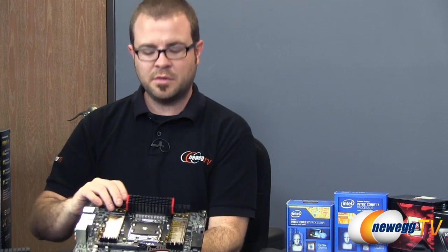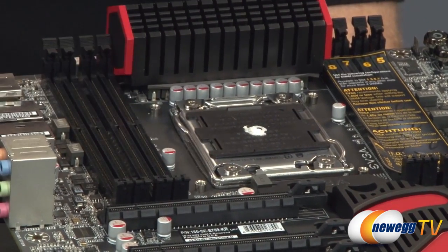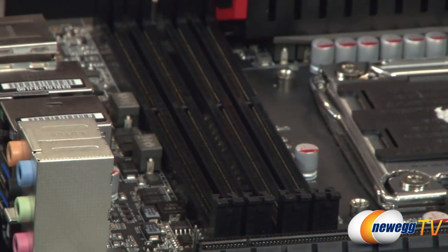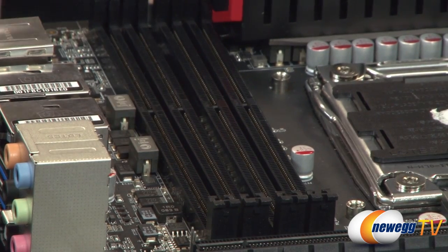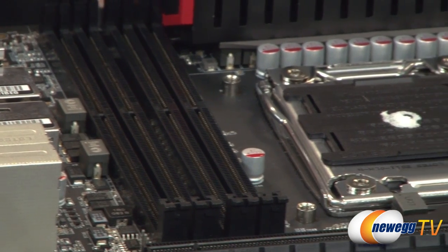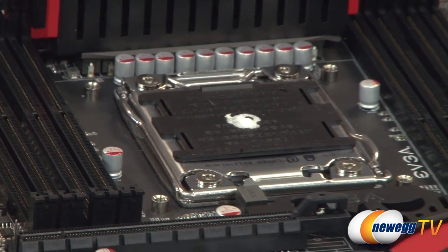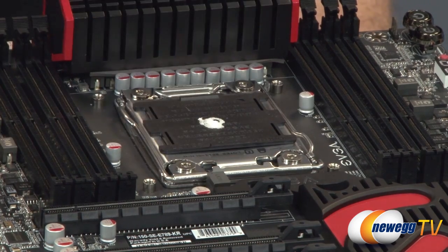For Intel's enthusiast platform right now, X79, right here, for example, it actually uses what's called quad channel memory. So let me pull a sticker off. You notice you actually have a total of 8 memory slots on this motherboard, and it's set up in sets of 4. Your motherboard manual will tell you which of those memory slots you should be populating with your memory kit. But if you buy a matched set of 4 with this, you can install all 4 of them, and that will give you, again, additional bandwidth that the CPU can access.